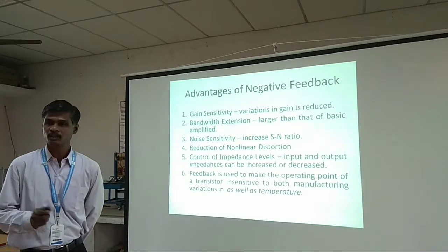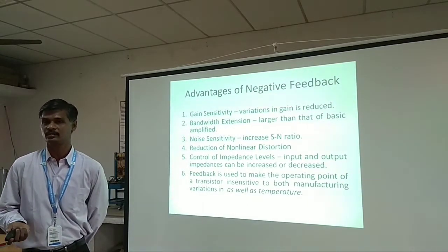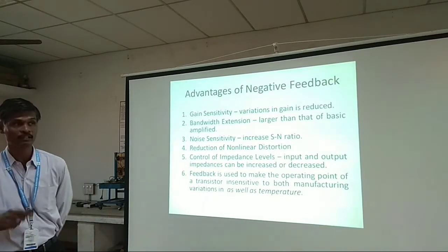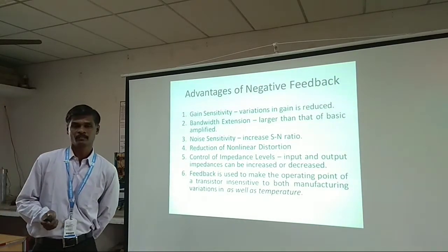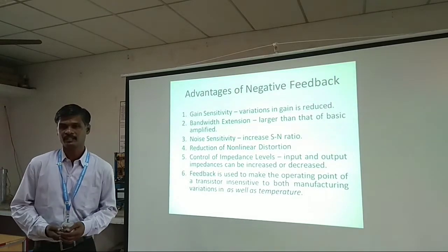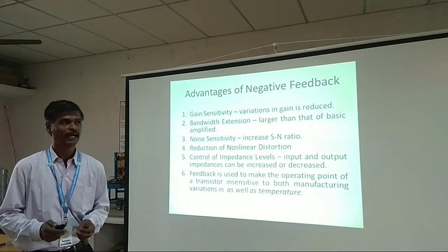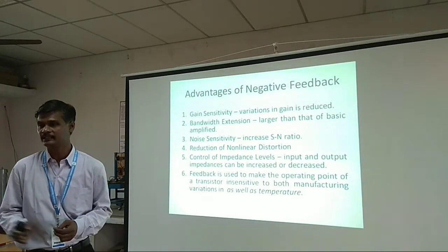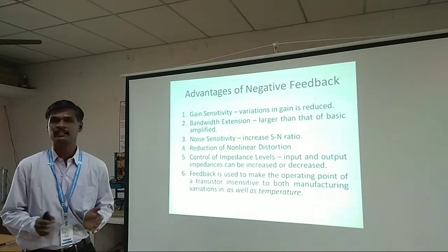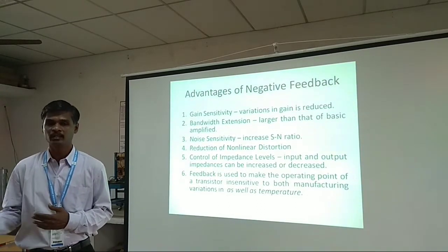When we go with positive feedback, this is not possible because the transistor will go to saturation and break into oscillation, and it will give you a continuous output. The advantages of negative feedback are gain sensitivity. That is, variation in gain is reduced with the help of negative feedback, and bandwidth can be extended to a larger extent. If you don't have feedback, then the bandwidth is very small, and if you have feedback, then the bandwidth can be increased further.